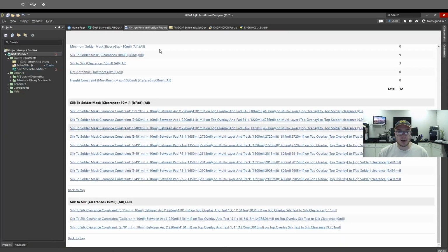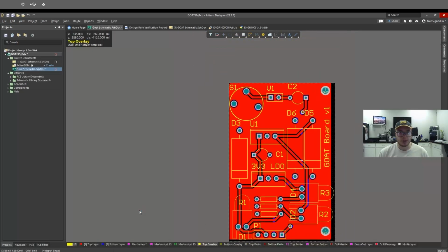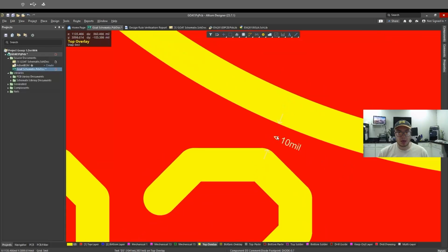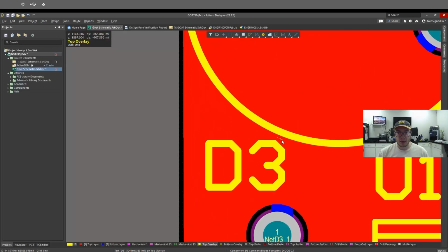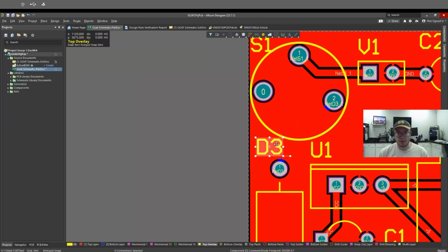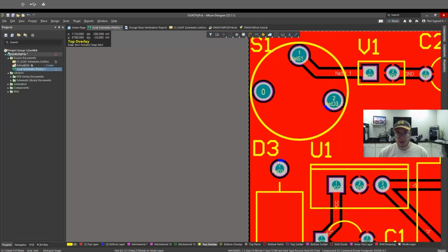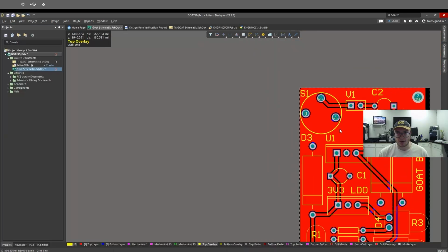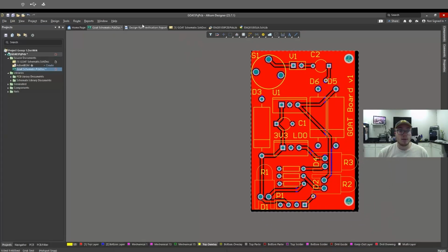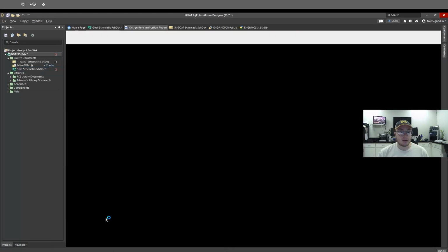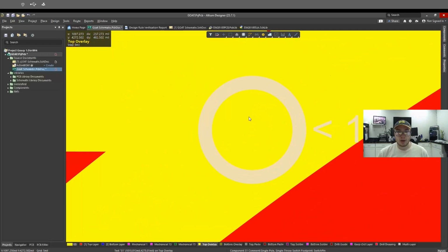And then if we look at our silk to silk clearances, same gig, again, less than 10 mil. I mean, we could move that a little bit, I guess. That's fine. Hopefully it doesn't then give us a rule violation there. That'd be awkward, right? And then we can look at this. Okay.